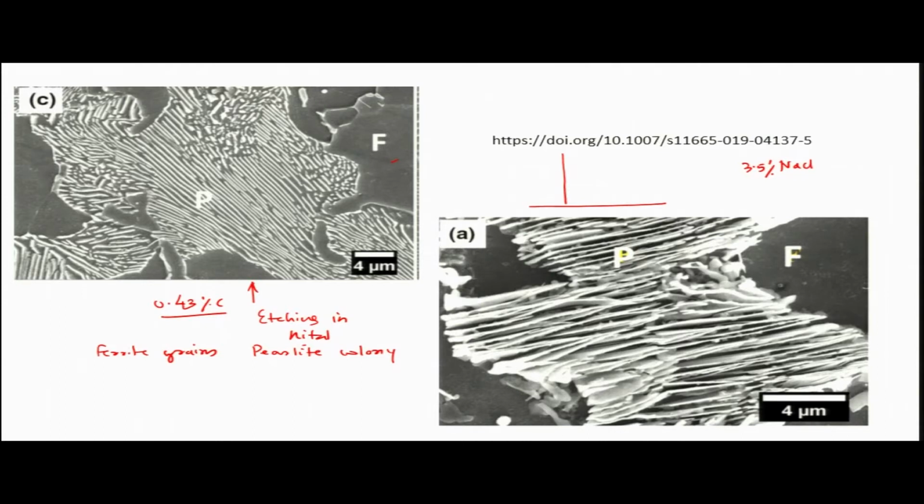Now, this is a micrograph which is developed after polarization. This is the kind of polarization we got at a very high value, in the anodic part, and after that we took the microstructure. Remember, after polarization we have not done any etching. This particular picture has formed due to selective dissolution of ferrite.